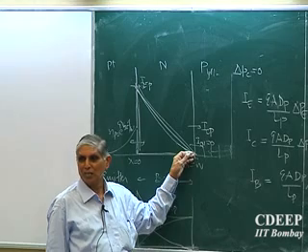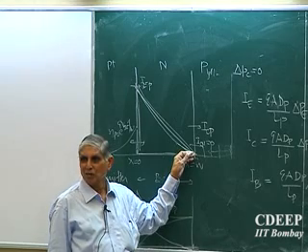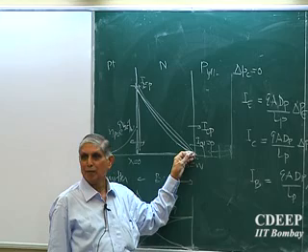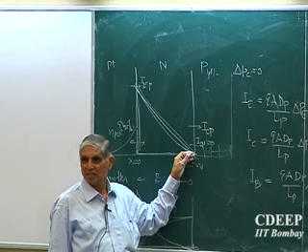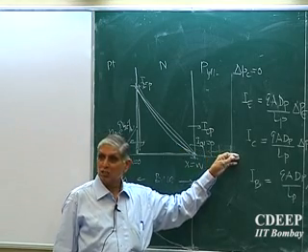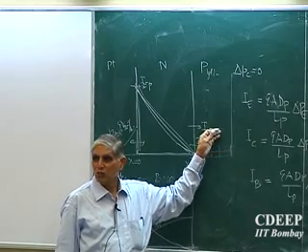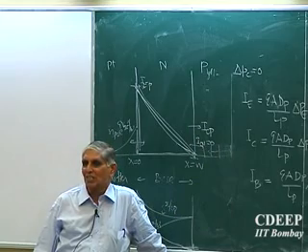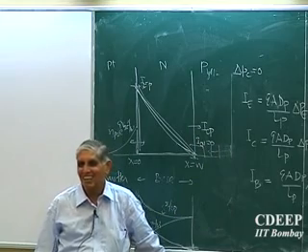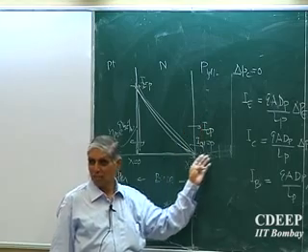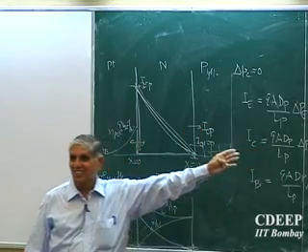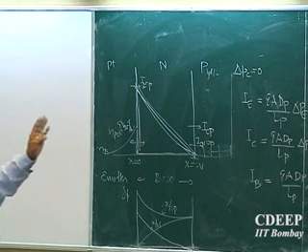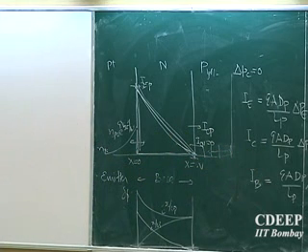and therefore we say breakdown has occurred. Is that correct? What is the breakdown? Which breakdown are we getting? Punch through. Okay, we'll get a punch through here. Is that clear? So the larger the collector length you keep, and the lighter you keep it, the device will stand larger voltages. So for a power device, what do we do? We make this lighter and take the length up to 100 microns, so that it can sustain up to 1000 volts without punch through. Is that clear how voltages are sustained? Because we increase the length.